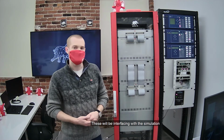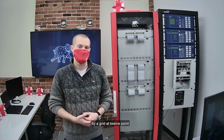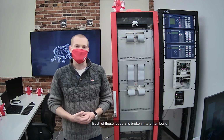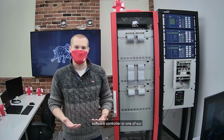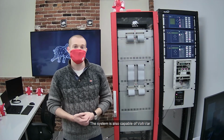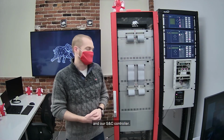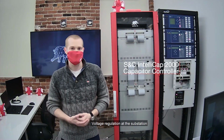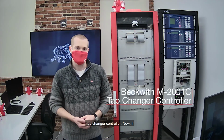These will be interfacing with a simulation of a distribution system, which consists of two feeders, each fed by a grid at 12.47 kilovolts. Each of these feeders is broken into a number of zones separated by feeder protection relays, and the two feeders are connected by an intertie. Each of our relays are controlled by either a software controller or one of our hardware controllers seen here at the top. The system is also capable of volt-var regulation, again through a combination of software controllers and our SNC controller. Voltage regulation at the substation level is handled with the Beckwith M2001C tap changer controller.